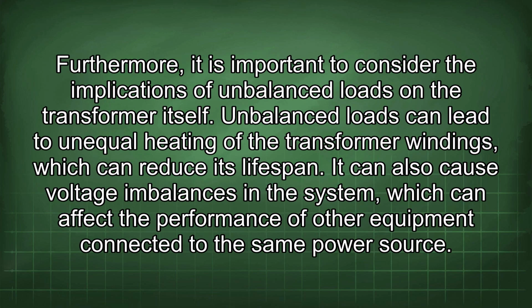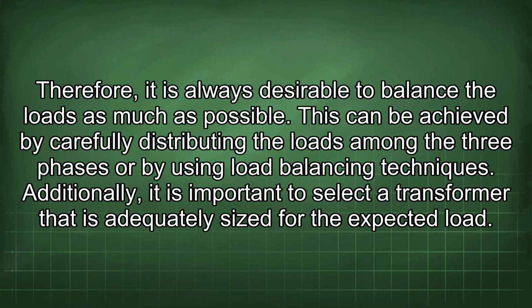Furthermore, it is important to consider the implications of unbalanced loads on the transformer itself. Unbalanced loads can lead to unequal heating of the transformer windings, which can reduce its lifespan. It can also cause voltage imbalances in the system, which can affect the performance of other equipment connected to the same power source. Therefore, it is always desirable to balance the loads as much as possible. This can be achieved by carefully distributing the loads among the three phases or by using load balancing techniques.